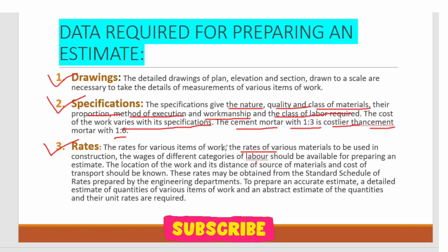The rates for various items of work, the rates for various materials to be used in the construction, and the wages of different categories of labor should be available for preparing an estimate. The location of the work, its distance from the source of material, and the cost of transport should be known. Because if you are constructing a building but the materials are not available nearby, and you are taking that material from a far distance, then you also have to pay some transportation charges.